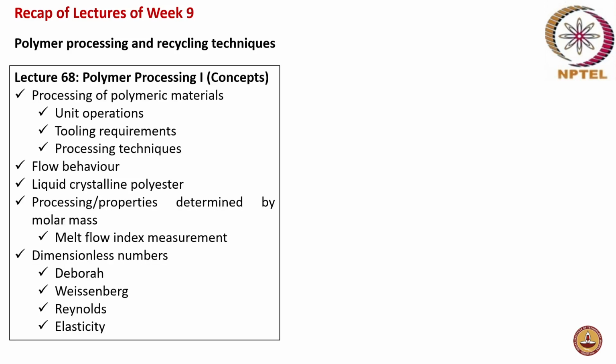The next lecture was on polymer processing. Here, what are the different unit operations involved in polymer processing? For example, you will have a mixing operation, and a plasticization operation, where some additive is used to plasticize the polymers. For example, to plasticize a homopolymer such as polypropylene, you will add a plasticizer. That was discussed. And then your melting operation, reactions, and the shaping operations, like you mold it or stretch it or pass it through rolls. And the solidification process. So these aspects were discussed.